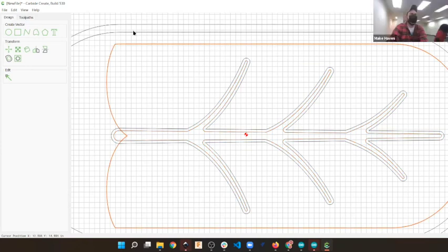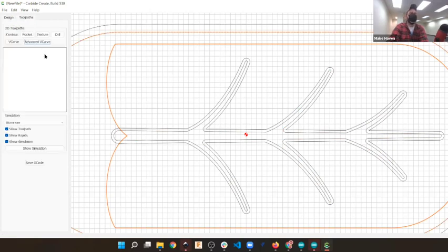No, it totally did. I think we got greedy in the toolpaths. We had five toolpaths for it to do it all in one go. I think it makes sense to do everything with a flat bit and export that G-code, and then it's totally going to stop. Then do another one where we export it with the round bottom bit for all the round bottom paths, so that they're totally separate and it won't automatically hop into the next thing, which it shouldn't do, but whatever, it did. And there are ways to work around it.